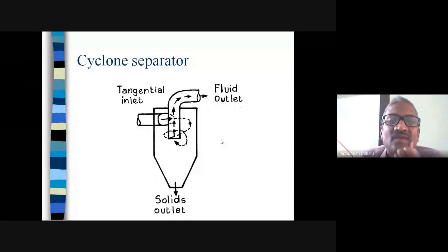When the cyclone is not created, all the material will go up and also come down without any separation. You need to create a minimum pressure to have the centrifugal effect. That is one thing. Too much centrifugal pressure is also not good, because it will cause blasting. Too much application of pressure is also not good.